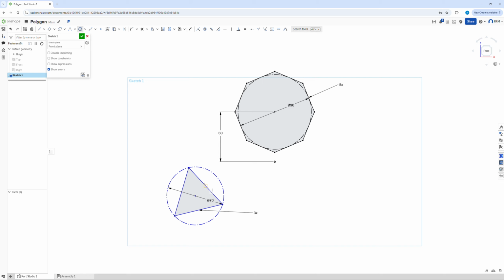So we're not actually dimensioning one of these faces. We're dimensioning the diameter from this point to this point to this point. So it's basically going across. If we wanted to change how many faces, we could double click on here and we could type in 5. Pentagon, we could want to go for that. It's up to you completely what you are doing.